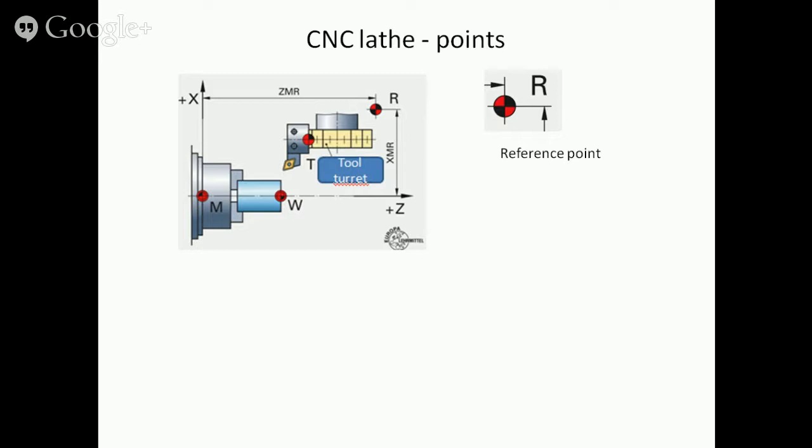Its graphic symbol is a circle divided into 4 segments: 12 to 3 o'clock black, 3 to 6 o'clock red, 6 to 9 o'clock black, and 9 to 12 o'clock red. On part drawings and in books, the red color is replaced by white color. Red is only shown here to give emphasis.